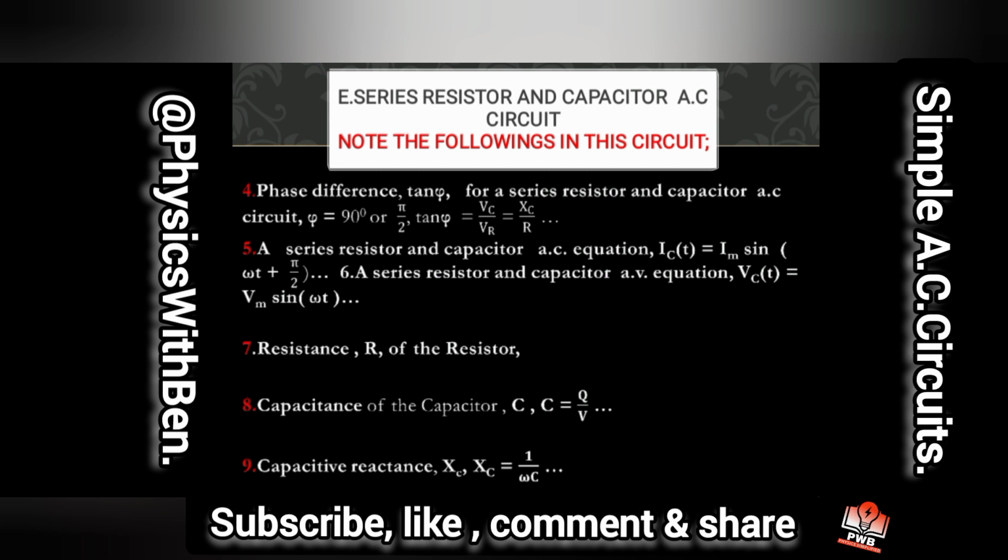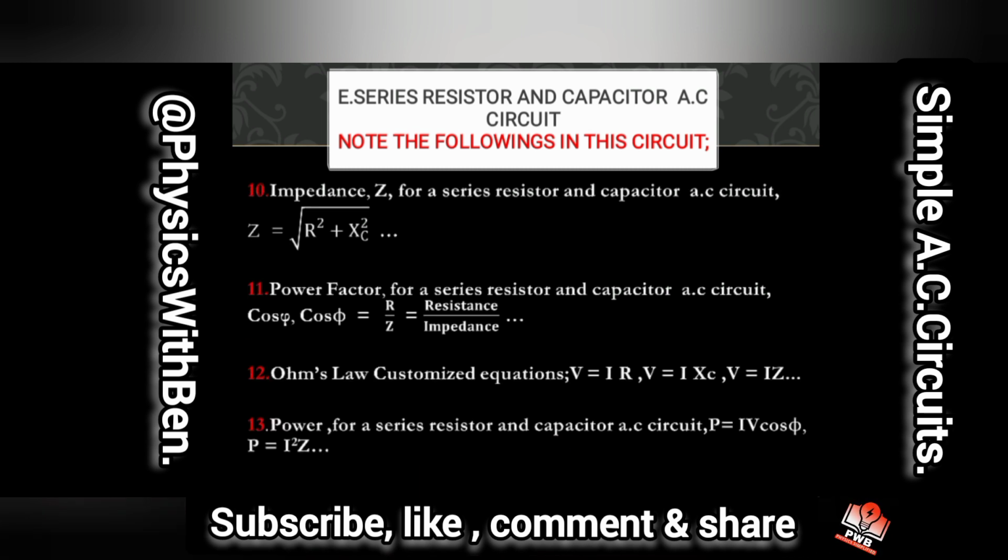So for a series resistor and capacitor, this is the equation. They may actually calculate the resistance, the capacitance, the capacitive reactance. Next up, you have the impedance. There's the presence of impedance here because you have the resistor and the capacitive reactance in place, and that gives us the impedance, the overall opposition to the flow of current offered by a resistor, a capacitor, an inductor, or both of them. So this is it, the power factor. The power factor is calculated as this.